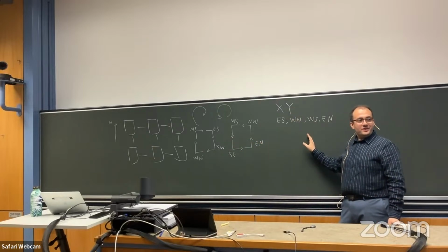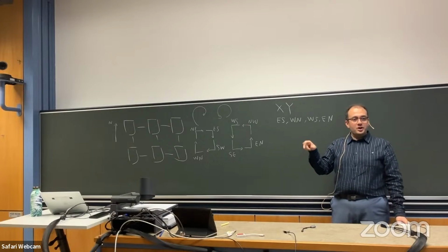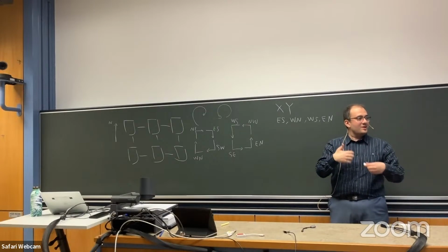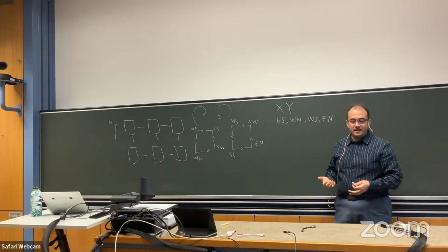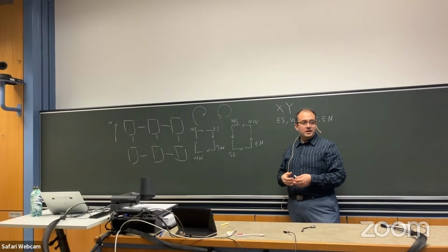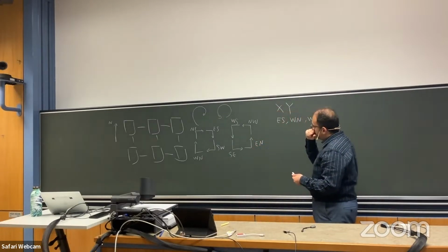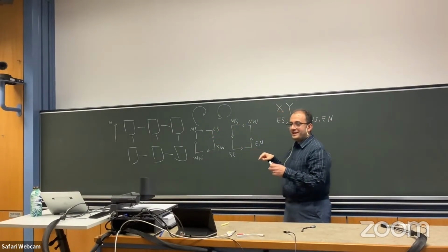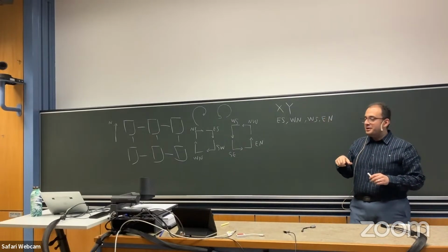That's why XY is deterministic. But we can make it partially adaptive, to use some path diversity, and it still does not allow deadlock. That's the concept of the turn model theory. For example, you can omit 1 turn from each of them, but that's not that easy because you need to be careful.